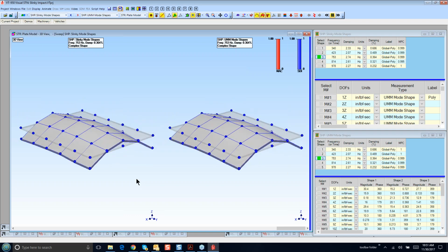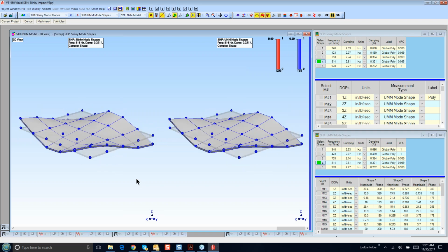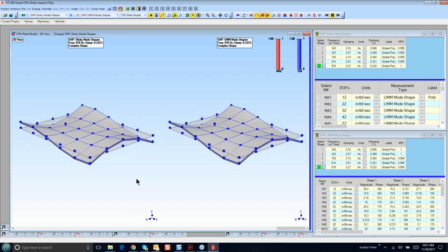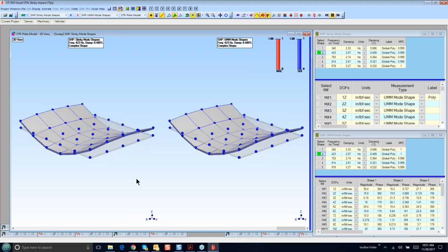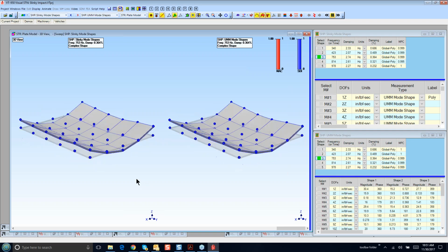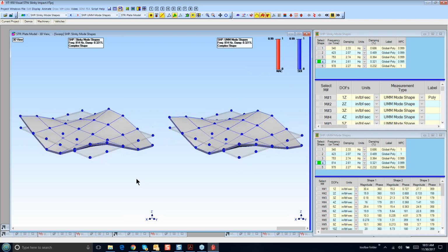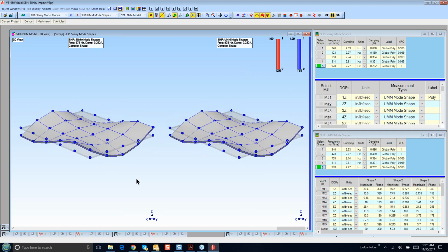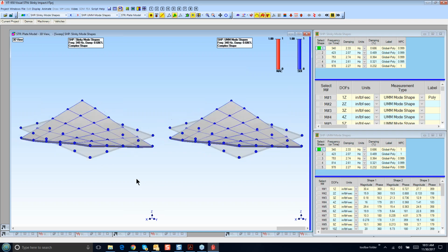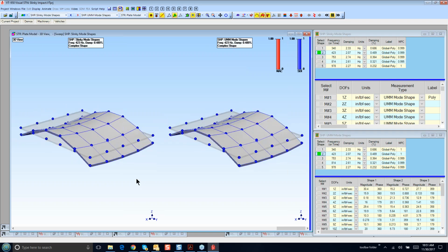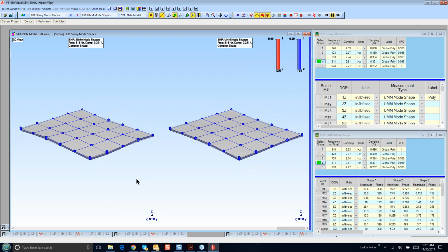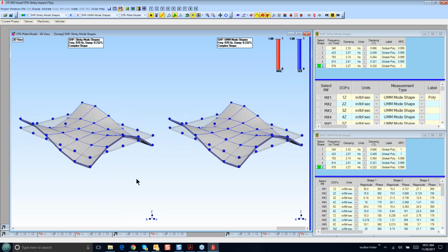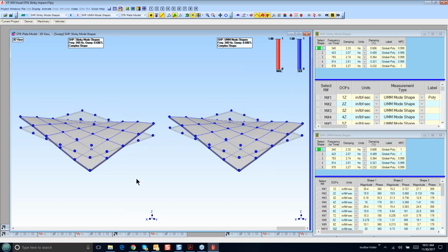The advantage of doing that is the experimental data includes all the boundary conditions, all the properties of whatever is causing a machine or structure to vibrate. We're actually measuring the true response of it. When we curve fit the FEA mode shapes to that ODS data, we are applying a fundamental property of any resonant vibration, and that is that the ODS data that we measure on a machine or a structure is contributed to by all of the mode shapes of the resonances. Another way to say that is that all resonances are excited at all frequencies. So we'll look at that both in the time domain and the frequency domain, and we'll talk about how useful that can be